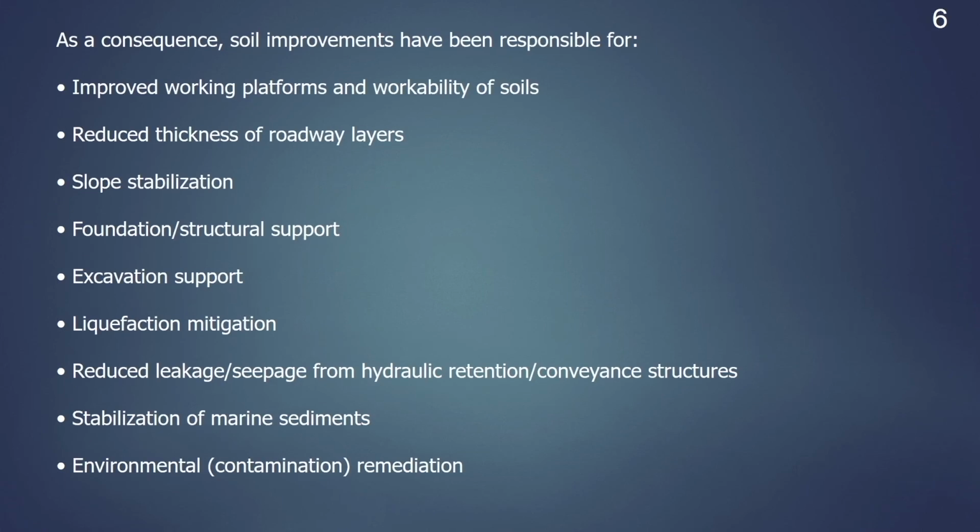As a consequence of all these chemical techniques, the soil improvements have been responsible for improved working platform and workability of the soils. It reduces the thickness of roadway layers. It provides slope stabilization. It provides foundation or structural support. It provides excavation support.